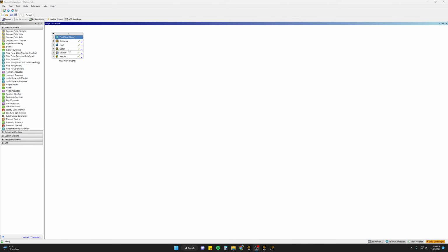So we can look at changing the inlet temperature. We can look at changing the size of the heatsink, maybe the total design power, to see how much we can force into that chip before we exceed the maximum temperature. If we wanted to do that, you can quickly duplicate this. We can right click on the top Fluent Flow title here, click duplicate, and this will essentially duplicate the setup that you have into a new setup. This will allow you to run it again. It will save your geometry and mesh and allow you to rerun your solution with maybe some new parameters.